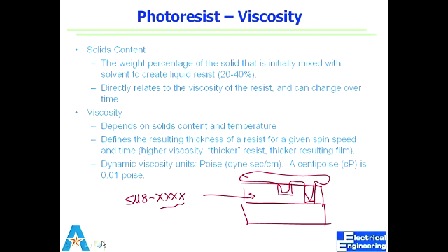Your wafer that you're using in your class, how thick is that wafer? 275. 275 micron? Are you sure? There's a tolerance, but the spec says it should be 250 to 300. So with tolerance, is that 275 microns? You can make a 200 micron thick layer on top of that from SU8, and you can make features in that. So that's something which is used. It's a very viscous resist.